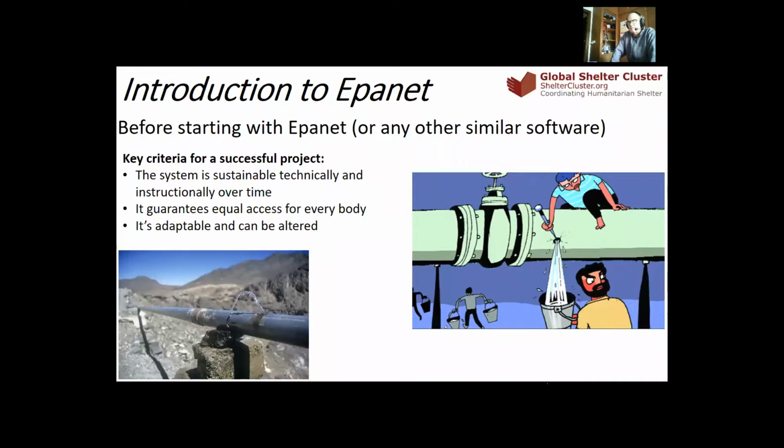If you don't give access to all the people, you will have the situation in the picture on the right, where you will have many illegal connections. And additionally, if you do a new network, you have to plan in advance about the development of your sites. If you size your network for 1,000 people, you have to calculate that the network would last for 20, even more years, and the population might increase accordingly. Therefore, you should size your network considering the development of the area.